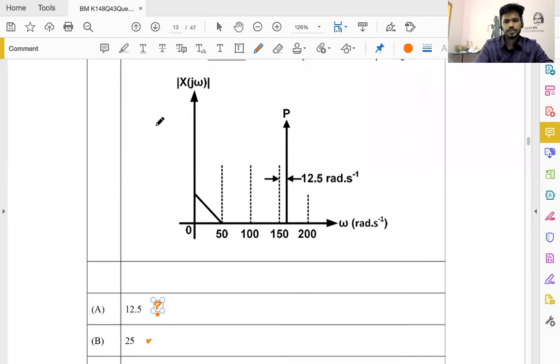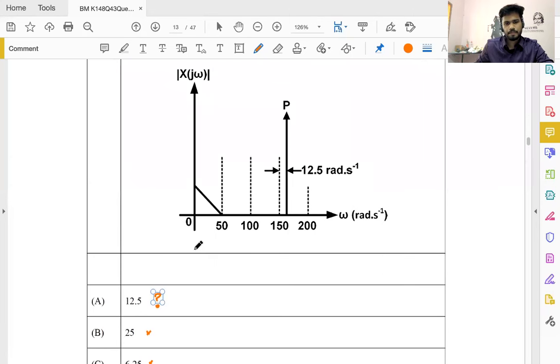I'm going to show the visual approach. If you're looking at magnitudes of the spectrum, you don't worry about signs. The way this transform happens is the function that maps any given signal, f input, to the downsampled signal, f output. That function looks like this.